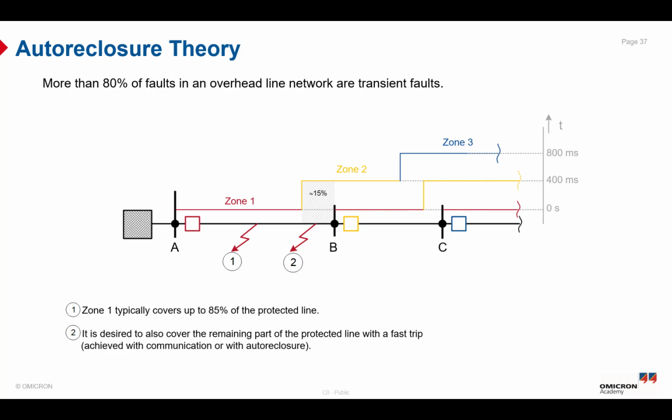For this purpose, the auto-reclosure function is used, and the principle of the auto-reclosure function is clearing the fault by momentarily de-energizing the line and fast reclosing of the circuit breakers in order to maintain the system stability and continuity of the service. But in cable networks, faults are not self-extinguishing, and that's why the auto-reclosure function must not be used with underground cables, and also must not be used with faults within transformers and generators, because the faults are not self-extinguishing.